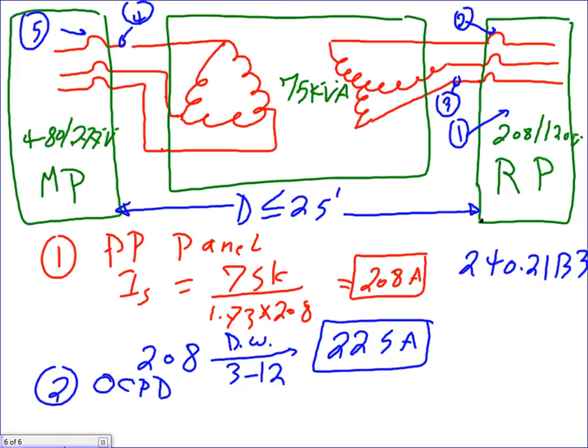Right at the secondary of the transformer. I hate to use 0 feet because you might have to do cover inside the enclosure attached to the transformer to be considered secondary protection of a transformer, which is right at the transformer. Utilities do it this way. They have an enclosure for fuses right at the transformer. That's why they have these rules, the tap rules. If you follow with me, I'll explain it in a second.